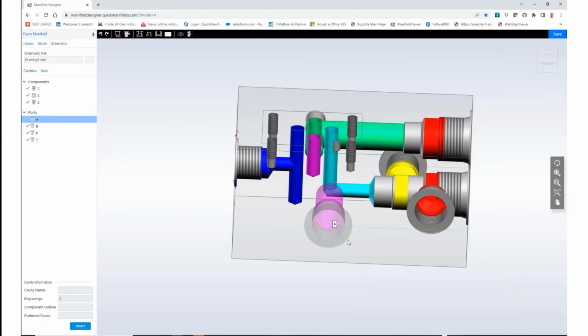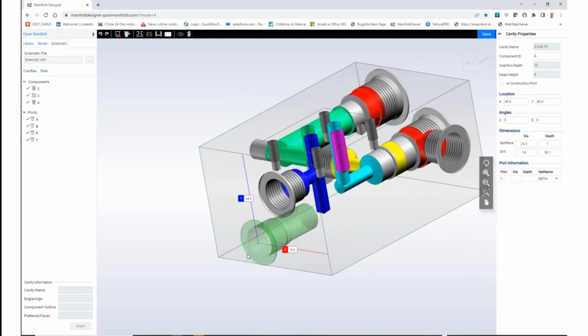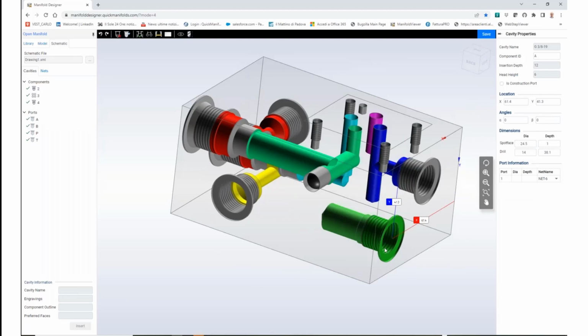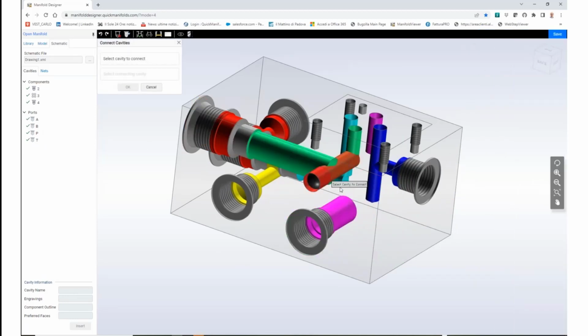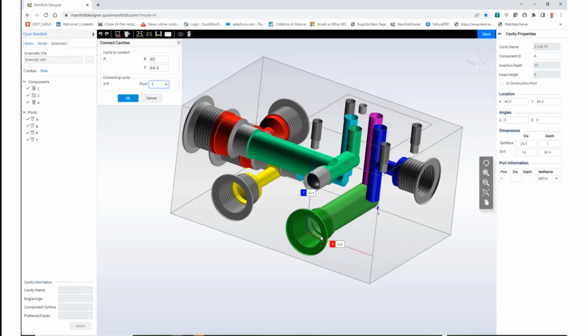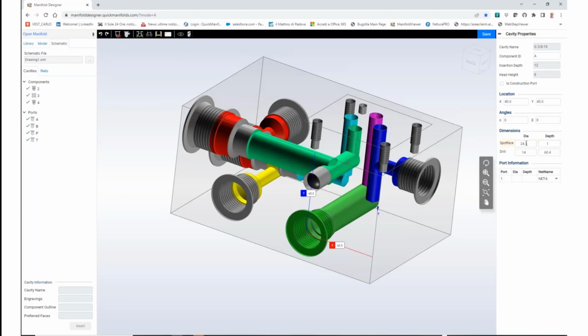And a port. Maybe a port we put on the opposite face. Down here. And we want to connect the A port with the pink line in a position of 45. Okay. And maybe we can reduce the drill. Let's keep it 8 millimeter.